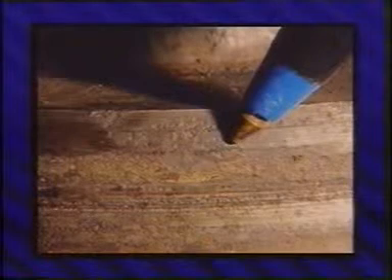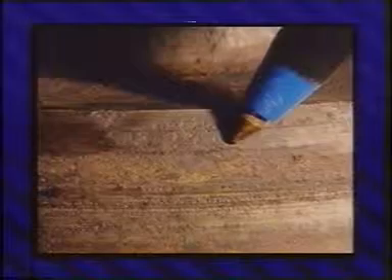Surface features of corrosion fatigue crack origins vary with the alloy and with the specific environmental conditions. In carbon steels, for instance, cracks often originate at hemispherical corrosion pits. Often these contain significant amounts of corrosion products. The cracks are predominantly transgranular and may exhibit a slight amount of branching. Except where they intersect the free surface, they resemble fatigue cracks that are not environmentally induced. Surface pitting is not a prerequisite for corrosion fatigue cracking of carbon steels. Corrosion fatigue cracks sometimes occur in the absence of pits.